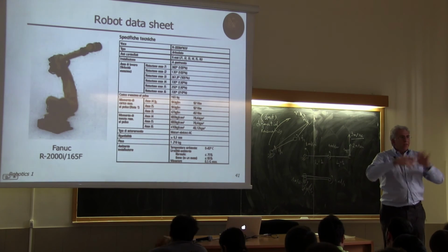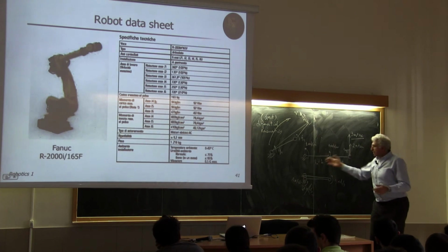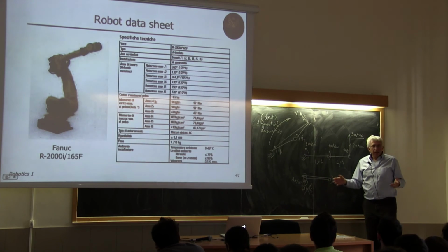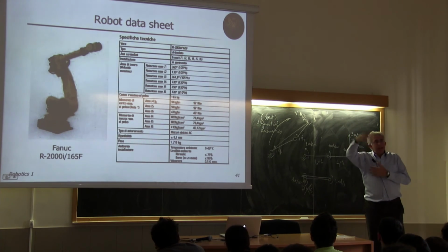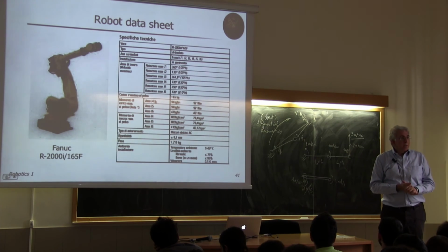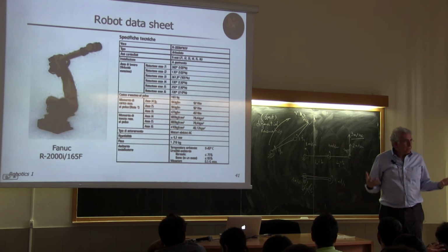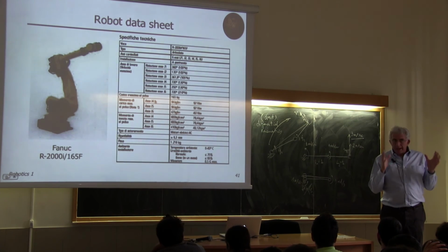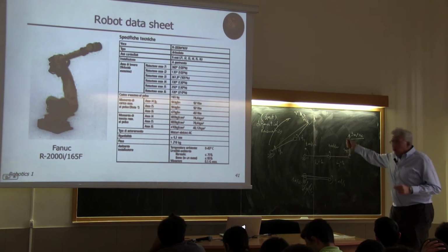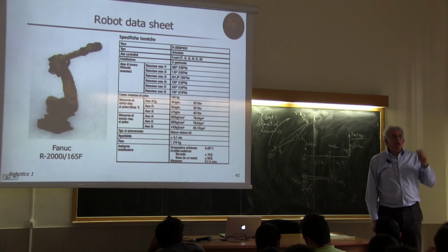So if I'm in a generic configuration, not as easy as this, which can be figured out very easily. I'm in a generic configuration with a 7 degree of freedom robot, and I'm giving generic velocity to each joint. The computation should be organized so that I get the solution in a clear form, not just going graphically like this. Okay? And this solution will be the Jacobian.